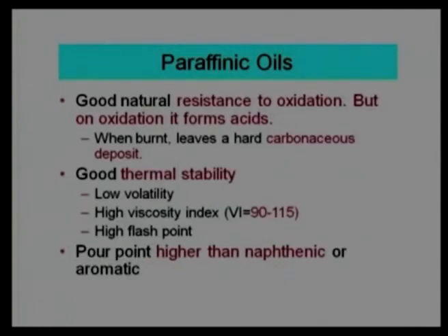Some merits and demerits of paraffinic oil. We say that paraffinic oil has a good resistance to oxidation. They are more stable against oxygen, but when they oxidize, they are not useful. They can corrode the environment or corrode the components which are in contact. In addition, they are not very thermally stable. When they are burnt, they make very hard deposits which can abrade the surface.